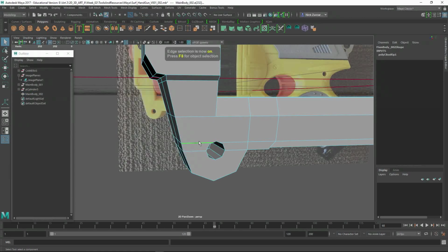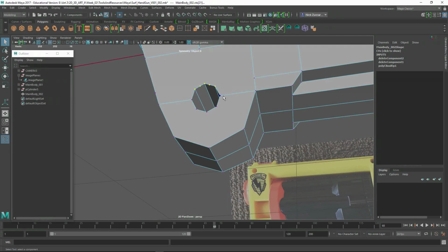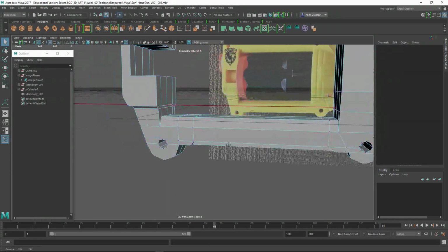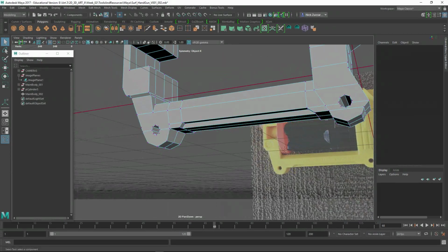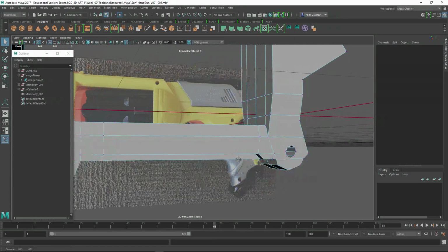Sometimes it's going to make some not so great geometry, so you might have to go through and clean some of this up, right? So I just selected those edges, delete them. That's going to clean up that part. Not that big of a deal for that. This part and through here, I probably don't want these edges, and then these verts, F9, so F10 edges, F9 verts.